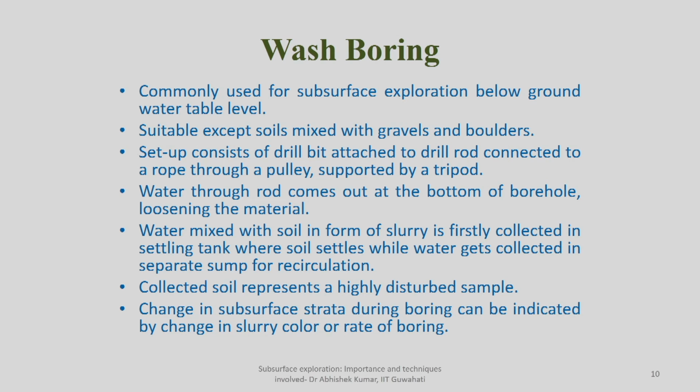So, in this method you set up at the site of interest where you are going to do some borehole, you put a tripod. From that tripod you lower some hollow drill rods. Within those drill rods at the lower end you will have some kind of drill bit or any arrangement which can scratch the material, and within that there will be a pipe which is connected to a pump. So, the pump is forcing water through the drill rod at the bottom of the borehole.